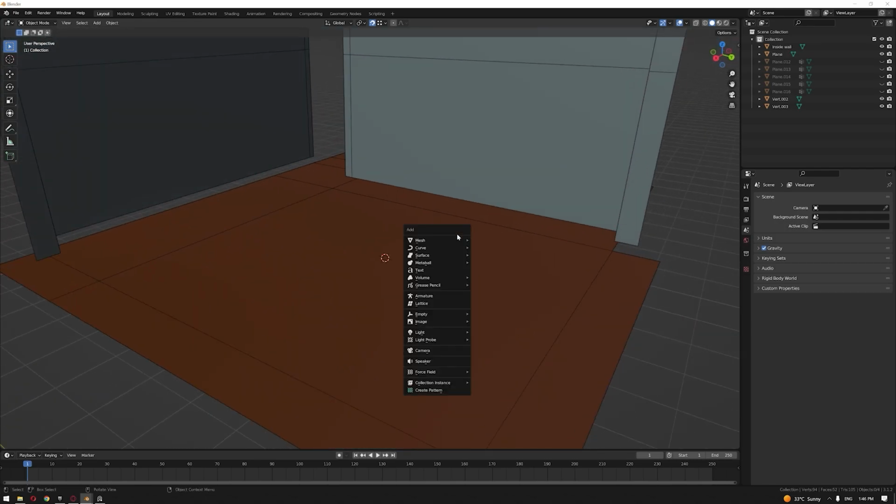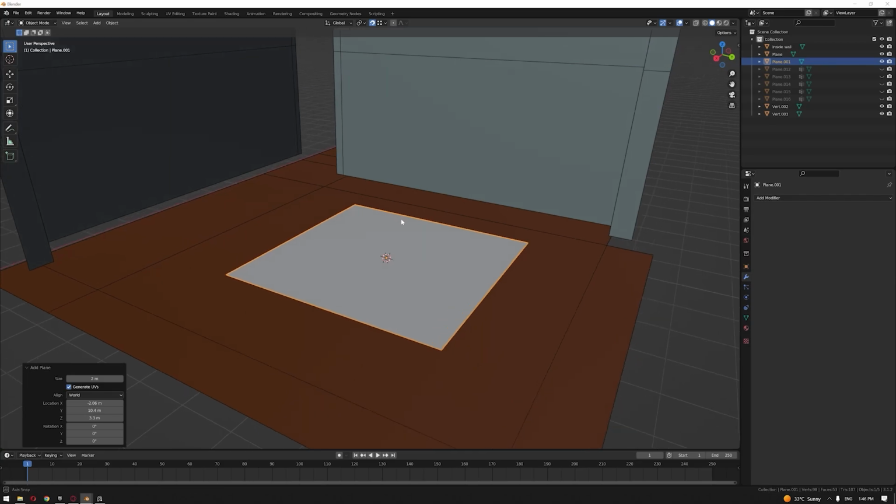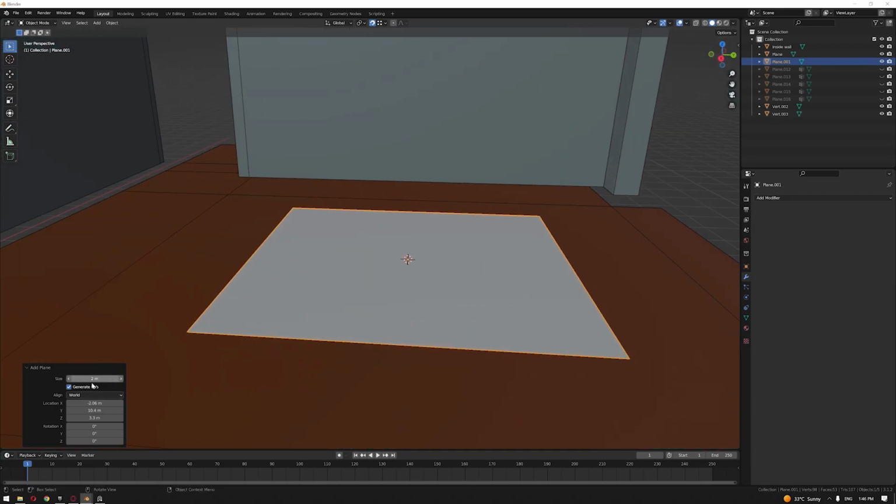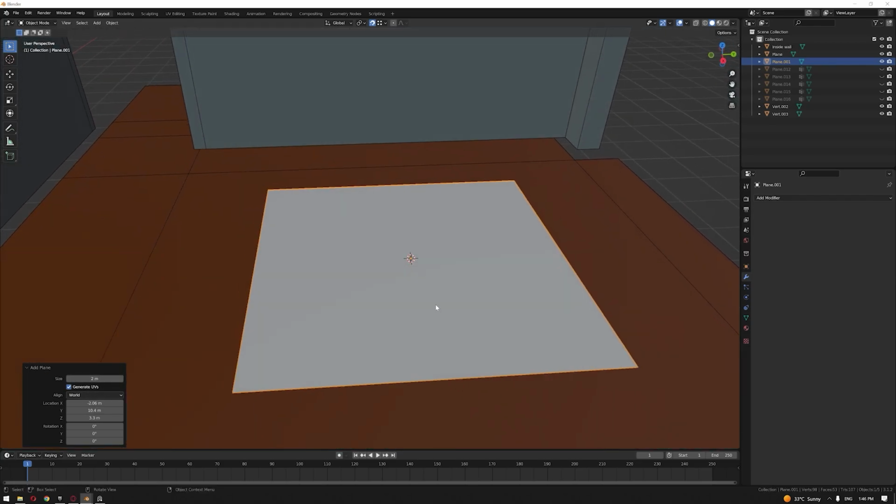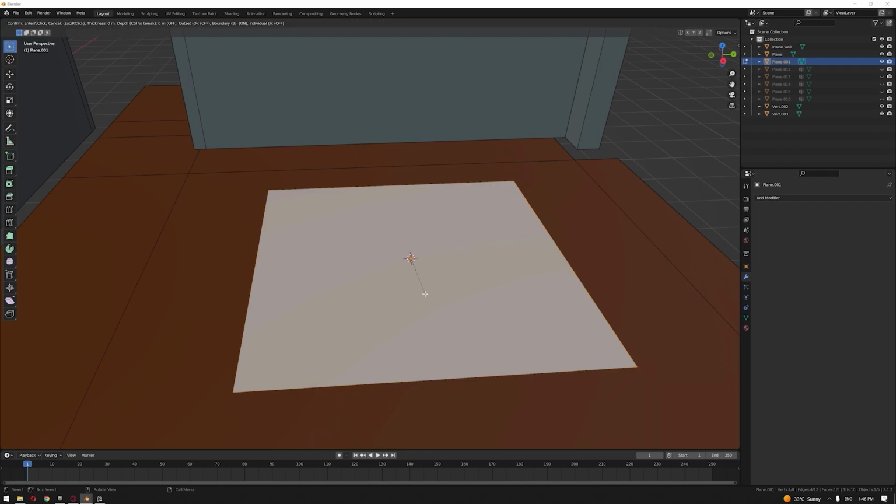So this is our target now, to develop the bed that you have seen in our teaser video. So let's add a simple plane, and this is going to be a size of 2 meters. Go into edit mode and then insert inward, typing 0.05. Separate the middle part as this is the mattress, and then choose the other part as well and separate them.